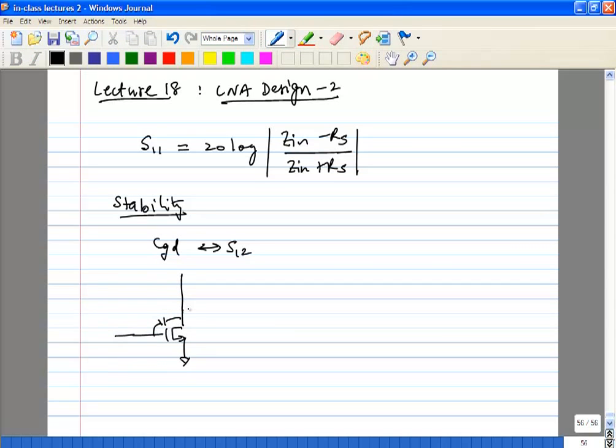One of the things you have learned is we use resonant circuits all over the place, right? So let's say we can tune out this CGD with a parallel inductor, but of course you can't connect it directly. You need a large capacitor, let's call it CB. You can use your inductor to tune out the gate drain capacitance. So that is one way. It's kind of a brute force way, but you can do it.